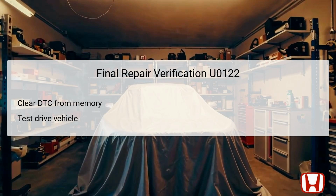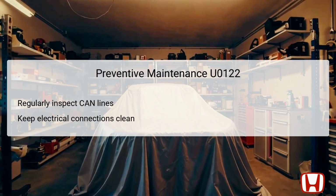Making sure that communication has been re-established between the TCM and the VSA is key to ensuring the reliability of the vehicle's electronic systems. Preventive maintenance is vital in avoiding future occurrences of DTC U0122. Regular inspections of the controller area network, CAN lines, should be a part of your maintenance routine.